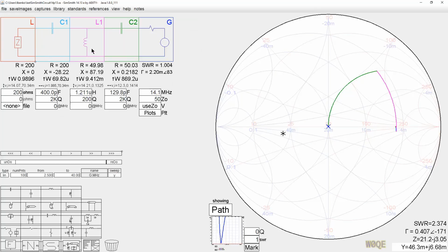In the 70s or 80s, when the T-tuner became really popular as a device to match networks, there were a lot of people who didn't like the fact that the T-tuner, which is a high-pass configuration, this particular T-tuner does a very nice job over the HF range with reasonable valued components. That was its claim to fame. With L networks, the inductance would get very, very large or very, very small in some cases. The capacitance could become huge. To match a 20-to-1 SWR on 160 meters, the capacitance could be as large as 8,000 picofarads.